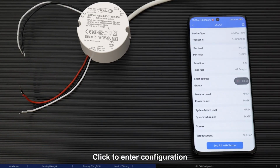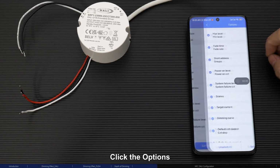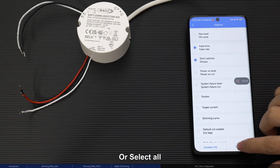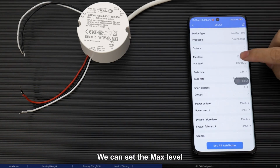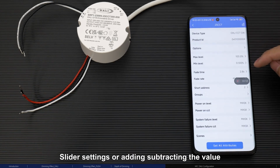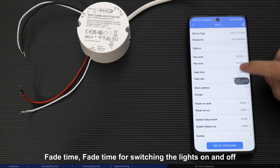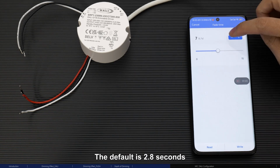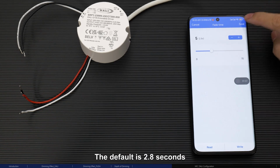Click to enter the configuration. Unlock it. Click the options. Select the configuration you want to modify, or select all. We can set the max level, slider settings, or adding and subtracting the value. Set min level, and the fade time for switching the lights on and off, and also for scene switching. The default is 2.8 seconds.